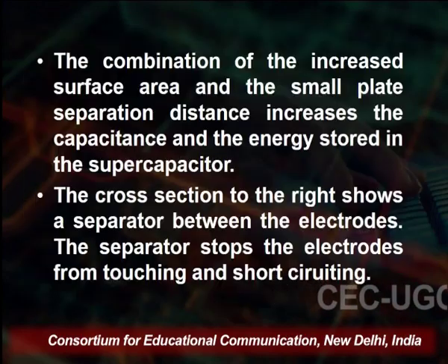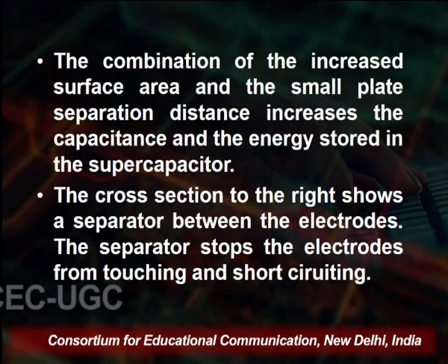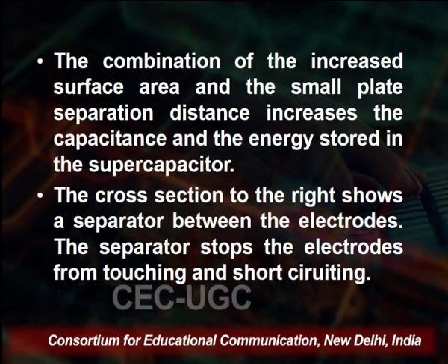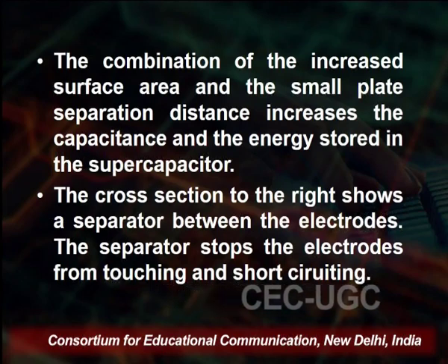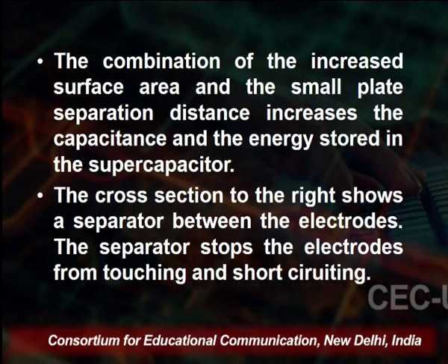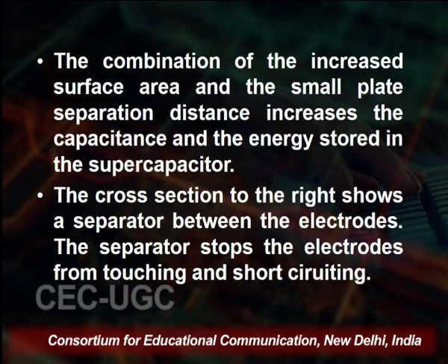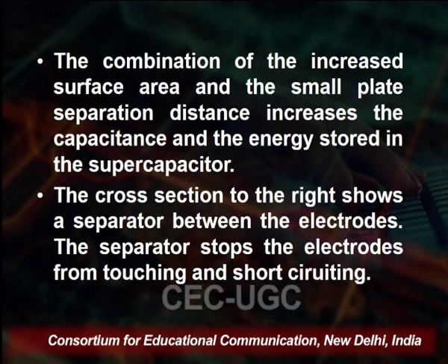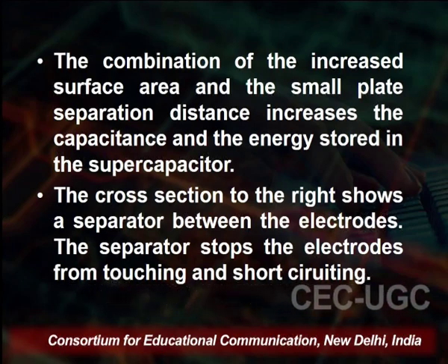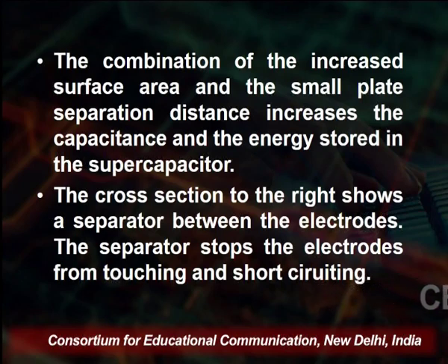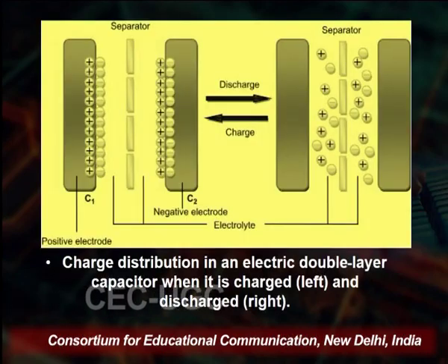The combination of increased surface area and a small plate separation distance increases the capacitance and the energy storage in the supercapacitor. The cross section on the right shows a separator between the electrodes. The separator stops the electrodes from touching and shorting the circuit.